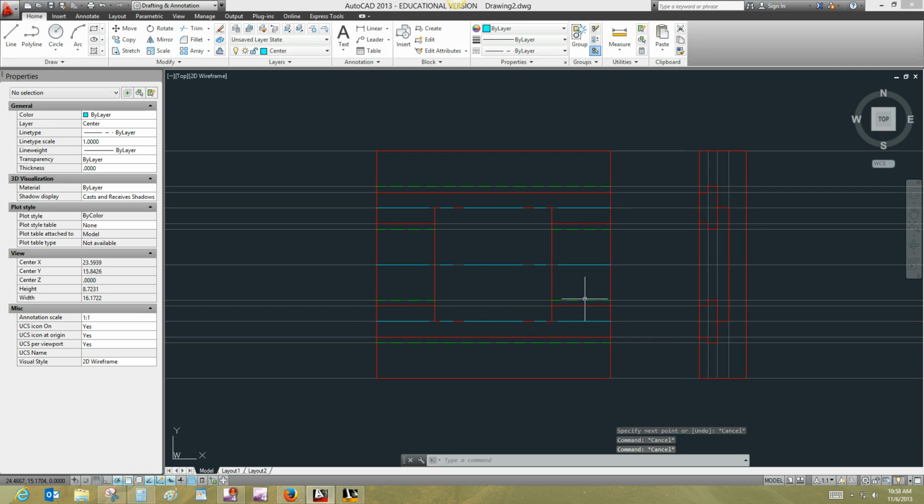Okay, so we have some problems. Center lines should extend beyond the visible edge, and depending on where you read or what object you're looking at, some texts say 1/8 of an inch beyond the visible edge, or 1/4 inch past the visible edge, and then some say it depends on the object, but all agree that it should be uniform. If you have a really large object, you may extend beyond the visible edge a different distance.